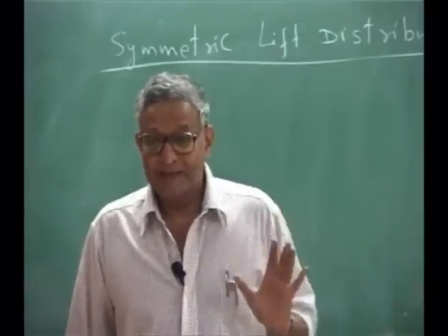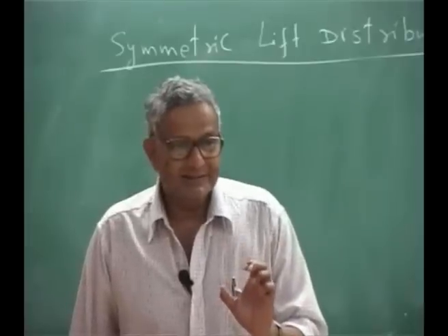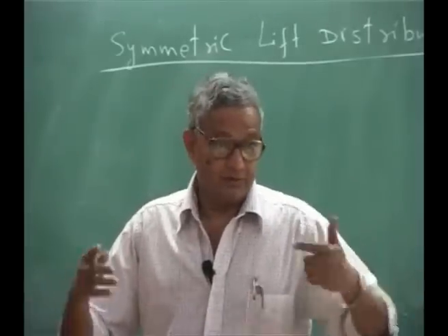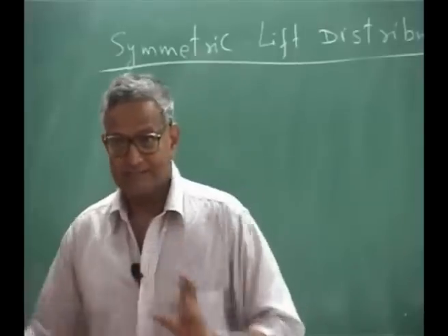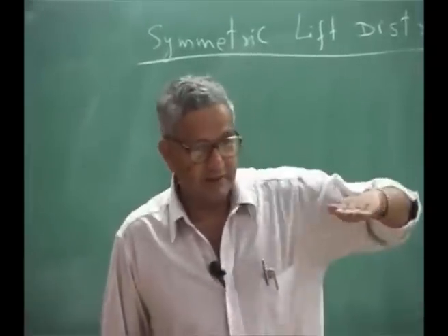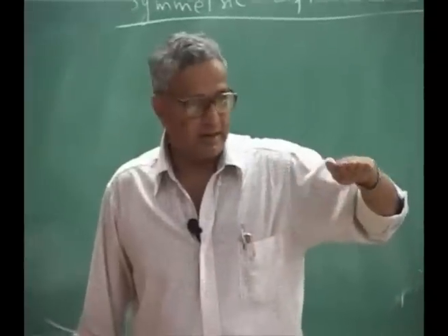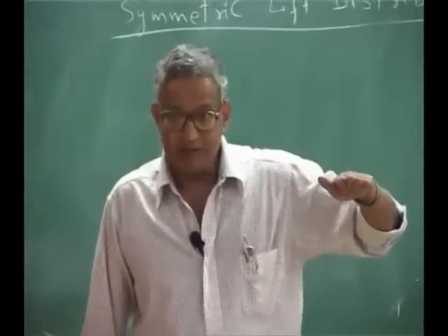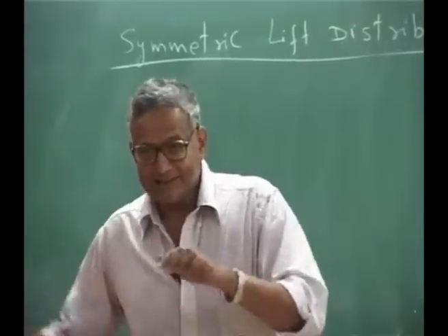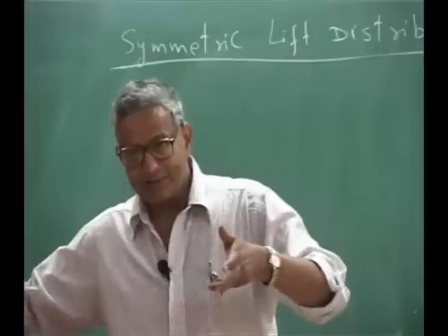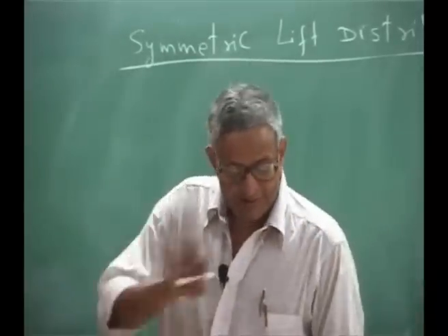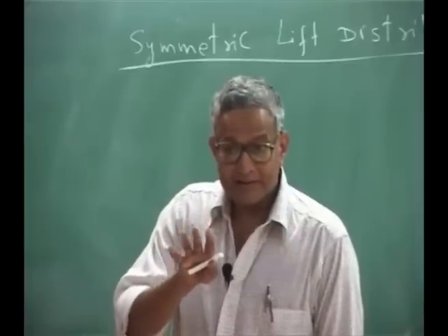Okay. Now, how much angle of attack I must give, which also takes into account the elastic twist of the aircraft, because this is very important. If you want to go in level flight, you must know what should be the angle of attack of the wing before elastic twist. After the elastic twist, the net lift will be equal to the weight of the aircraft in level flight. So there are two types of problems that exist.